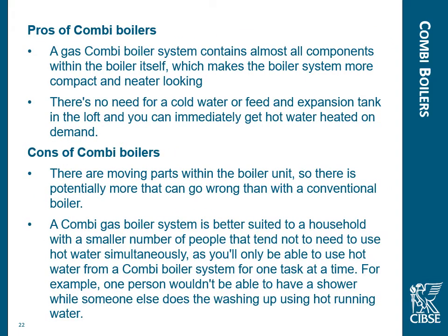The good thing about the combi boiler is the system contains all of the components within the boiler itself, which makes the boiler system more compact and neater looking. No need for a cold water feeder expansion tank, so that's good because storing water in the loft is what we used to do years ago, but we've moved away from that now, perhaps with Legionella disease in mind. And also in our loft areas, we tend to occupy that area because space is at a premium nowadays, either at home or for offices.